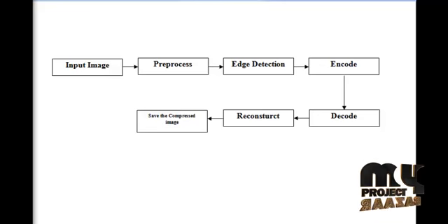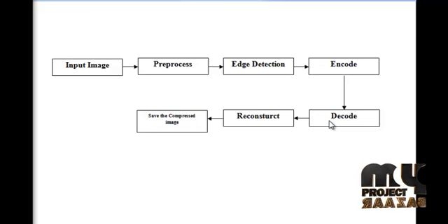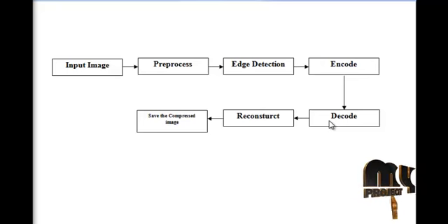The pixel values between sampled points are computed by using linear interpolation along each edge. Higher order interpolation does not give any advantage since the pixel values hardly vary along one edge. The decoded pixel values have to be placed at the corresponding positions in the final image.